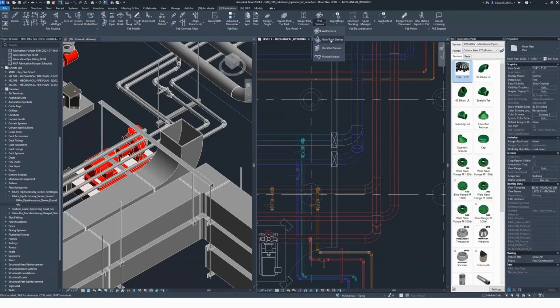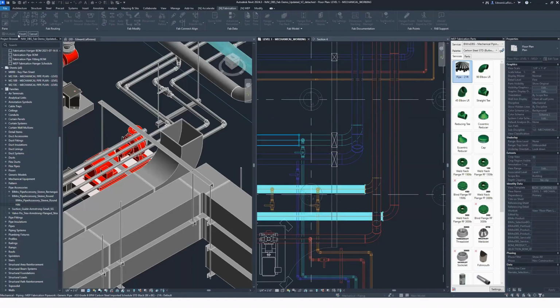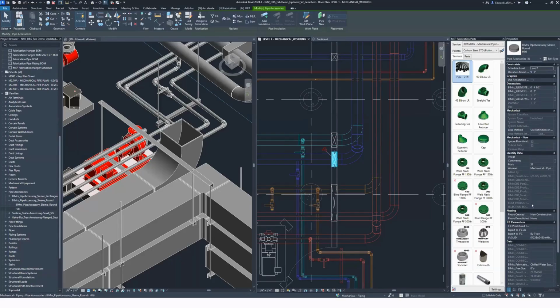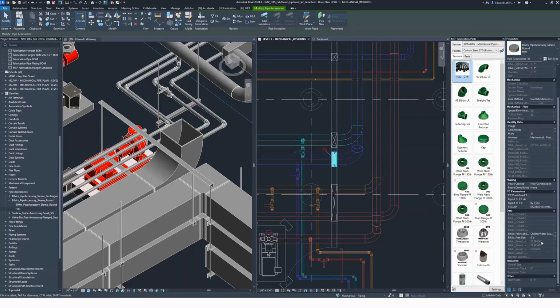We do also support blockouts, floors, and roofs, and a manual sleeve if you don't actually have a link available. Same exact process, choose the elements you want, place a sleeve around them, using host size to size it, using wall type to determine which one we need. Really slick stuff. And like I mentioned, we're putting all that good data inside as well. So that sleeve's sitting down here with X, Y, Z's, free size, and fab service all ready to go, ready to tag. Those are all shared parameters for you to leverage.